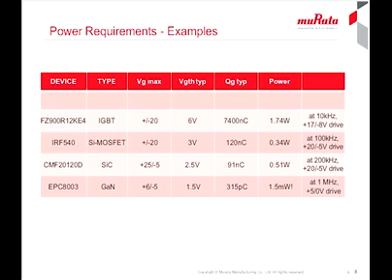For example, the large silicon carbide device from Rohm is the BSM300 series. It has a gate charge of 2 microcoulombs at 25 volts. If you switch this device at 400 kHz, you would need 20 watts of gate drive power. Don't forget that the DC-DC may also be providing power for fault detection and signaling, so this will add to its load.